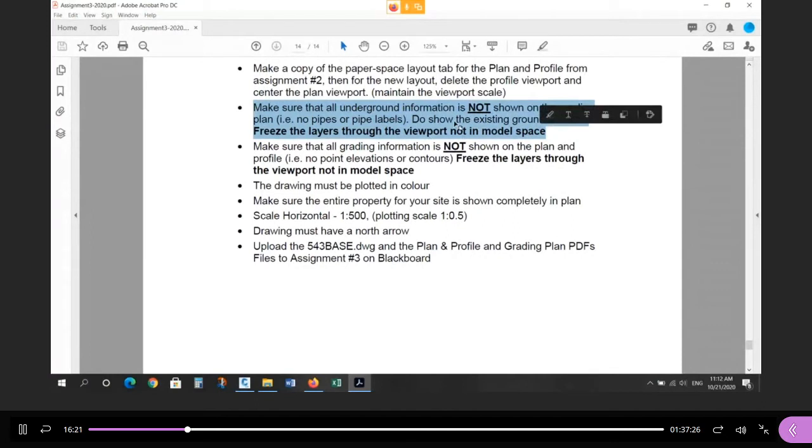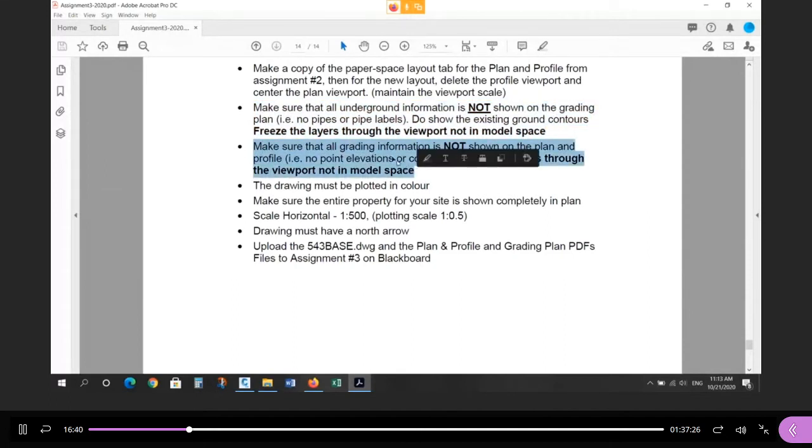The specification for that, if it's not here, just show it whatever you want. I think I asked you to create contours later at I think a quarter meter and 1 meter, right? But I wasn't specific, so do whatever you like. Certainly show contours, not the 3D TIN lines, right? And then on the grading plan, make sure there's nothing related to underground stuff. Nope.